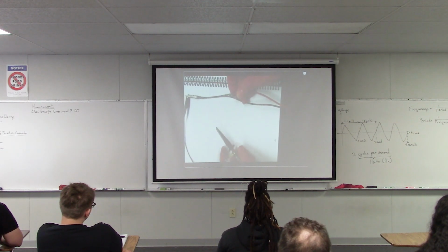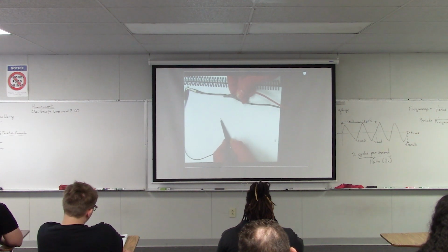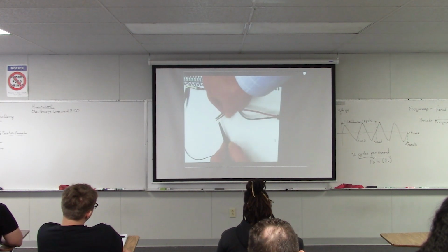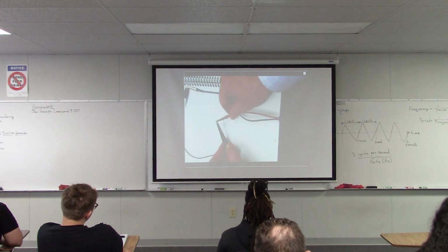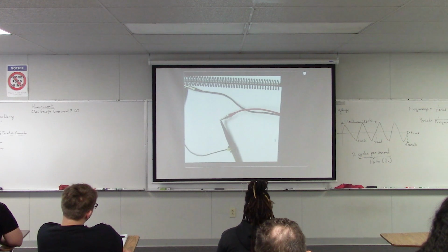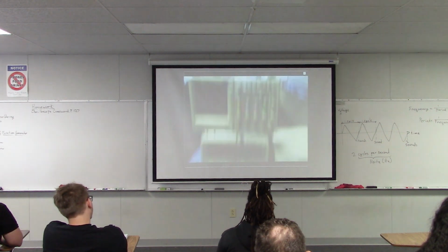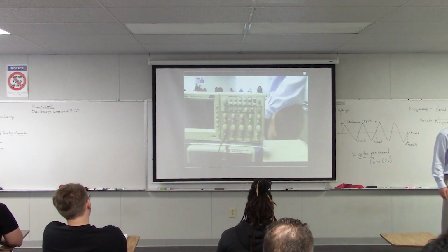The way that you access the probe on the oscilloscope is that it has this little sleeve around it. So you grab the bottom of the sleeve and you pull backwards, and then that exposes this little hook at the end of the connector there. So you're going to do that, and then you're going to clip the function generator lead onto that little hook to make a good connection. So now we've hooked the function generator directly to the oscilloscope. Now we can actually power these on, turn them on, and see how they work.